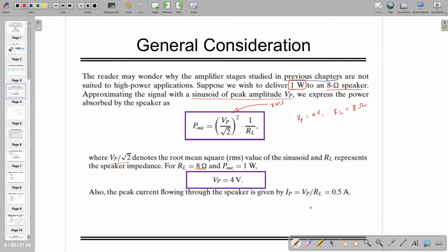Nowadays, I have seen that some of the people have migrated to different technologies. Instead of CMOS, instead of silicon, they are moving towards gallium nitride or some power MOSFETs, so that they can drive the output, which is actually as low as 1 ohm of resistance. So that is a very challenging part over here, and we need to design accordingly.